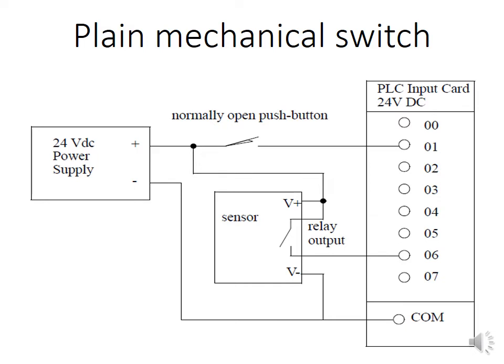The sensor is connected as part of the circuit loop and in such a way that it is able to close or open the circuit depending on the state of the phenomena being measured or being detected. When the circuit is closed, there's a flow of current through the receiving circuitry. When the circuit is open, there is no flow of current through the receiving circuitry.